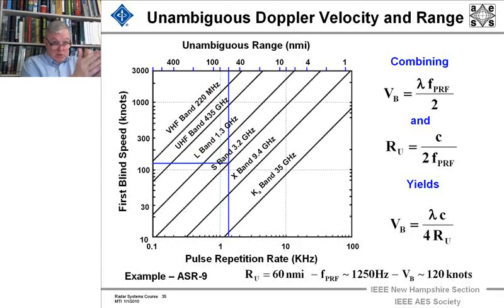angular resolution, you want a small angle. Angle is related roughly to lambda over D. It points to X-band or higher if you're going to put a radar in the nose of a fighter. So you can see how what we're talking about are factors that come into strong play in the design of radar waveforms.